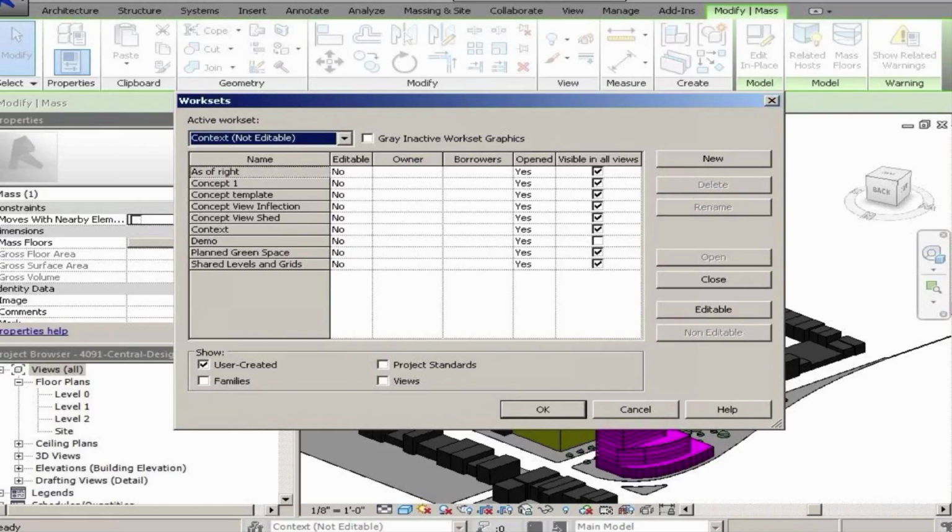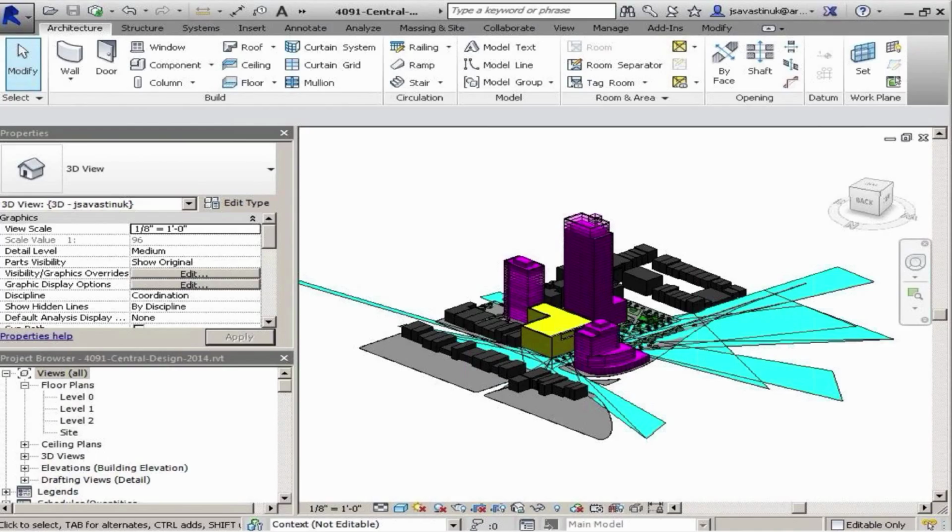So I would have the team set up a series of work sets, and because I've been doing this for a while, I still use work sets a little bit like layers. I know that's not the best thing to say, but I still do it. And we would set up a series of work sets that the team could bring in and effectively isolate the objects or the groups and masses that we just created in the FormIt model. And this is how the team would set that up. And this is the sort of final result of that.